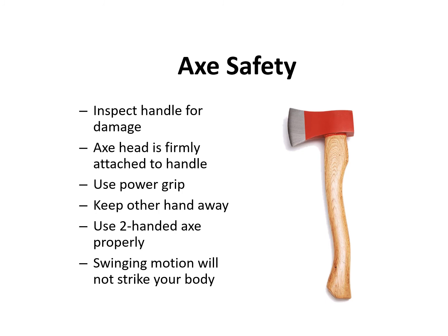When using an axe, inspect the handle for any signs of cracking or splits. Make sure the axe head is firmly attached to the handle. Hold the axe with a power grip, which includes all of your fingers wrapped around the handle. Keep your offhand away from the axe strike zone.